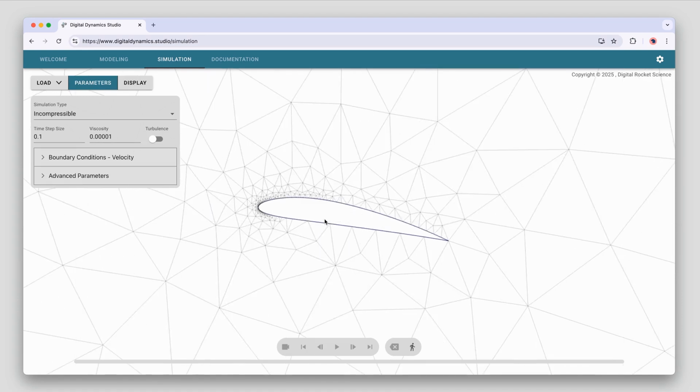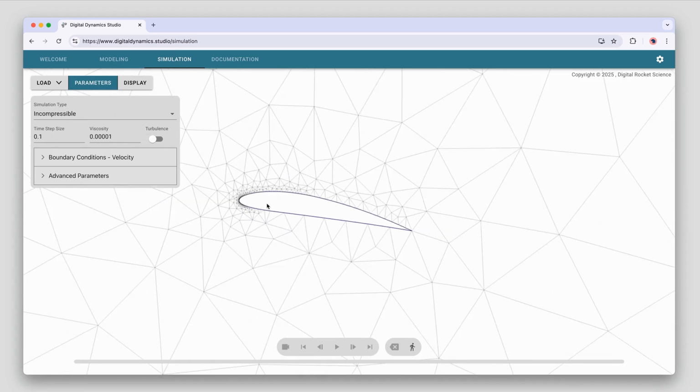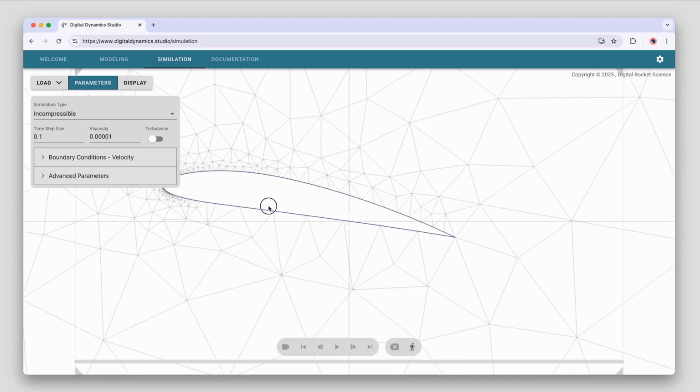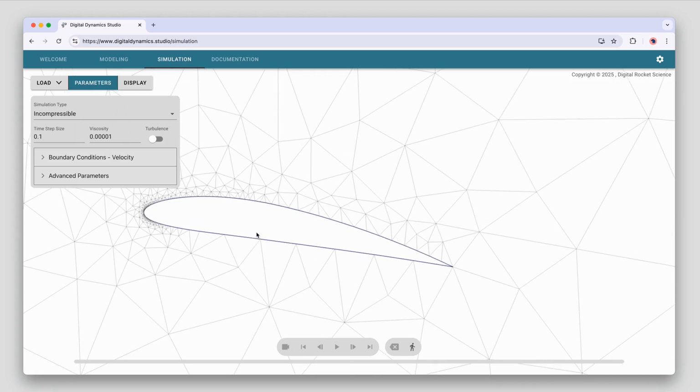In those kinds of flows, there are problems that arise. Number one is called turbulence. Not turbulence like you would feel flying in an aircraft cross country when you hit some bumps. That's not the turbulence that we're talking about here. It's just that the fluid becomes very chaotic and unstable at higher Reynolds number, and the features of the flow become very, very small in certain areas, almost microscopic. That's called turbulence.